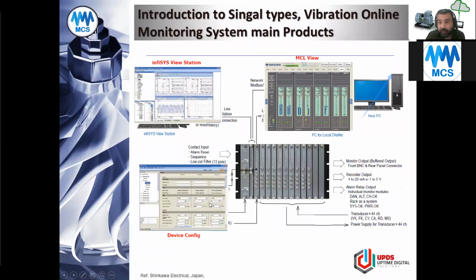This is exactly the full view, except the machine level or the transducer level, where you can put the sensor here. Then after that, you connect it to the rack, and afterward you will configure it, then you can control it and view it in the HMI or SCADA system, and you can control it later on in a dynamic system or VMS system to analyze what's similar, like what Mr. Salah discussed: the orbit, shaft centerline, full spectrum, and so on. This will fall on this level.